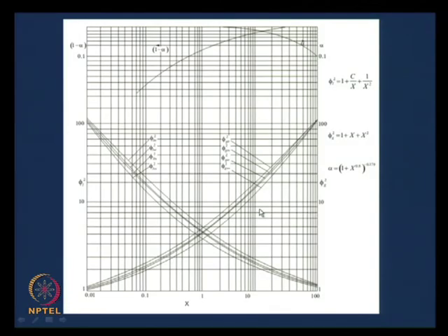Okay. Now, you just remember certain things. This particular correlation which I have shown you is used specifically for horizontal flow without phase change. So, therefore, it is more preferable for air water, for steam water flows. It has not been derived for that particular situation. The correlation was specifically derived for horizontal flow without phase change or significant acceleration, and it can be used to calculate both the void fraction and the frictional pressure drop, even when these effects are not negligible also. It can be used. Okay.